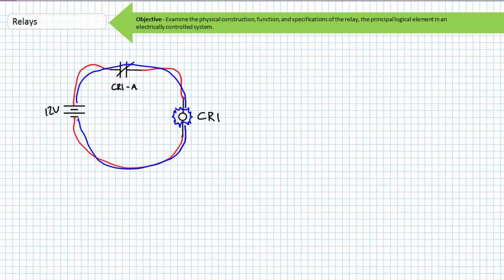When energized, the associated contacts change to their opposite state, and the normally closed contact opens, de-energizing the coil. When the coil de-energizes, the normally closed contact returns to its deactivated state and energizes the coil. Repeat as necessary. You would not ordinarily wire a relay in this fashion unless you wanted to create a buzzer.